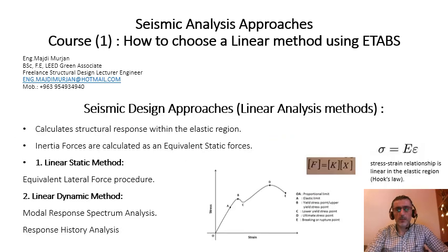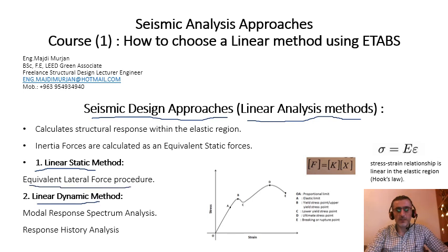Now let's talk about these approaches, linear analysis methods. We have the linear static method and linear dynamic method. Linear static method, ELF procedure, equivalent lateral force procedure. Linear dynamic, we have modal response spectrum analysis, response history analysis.